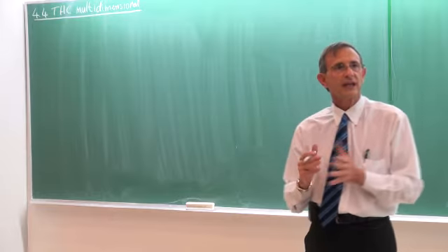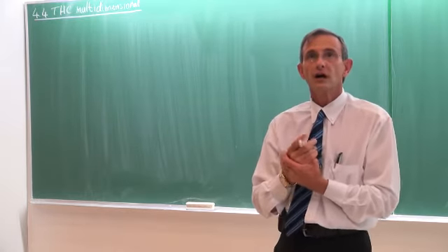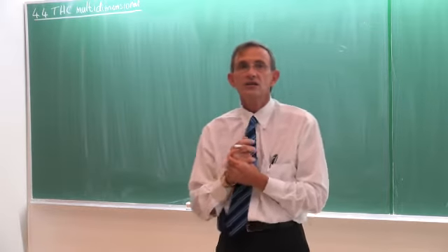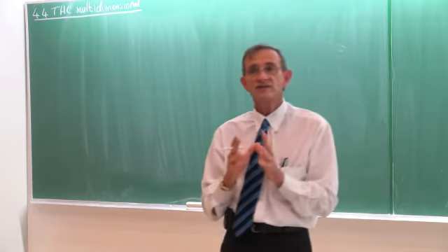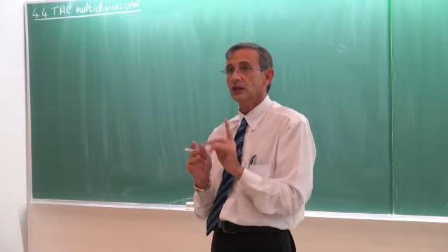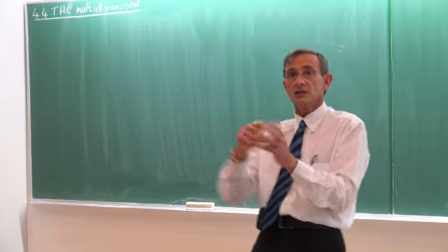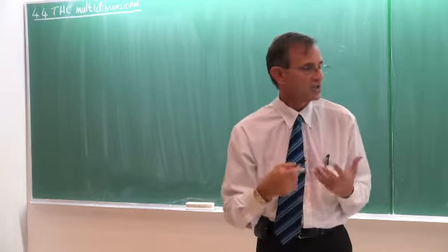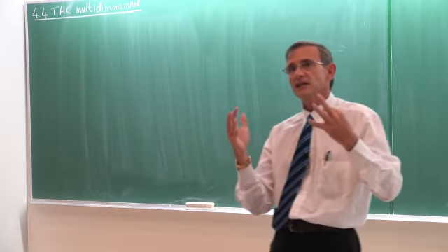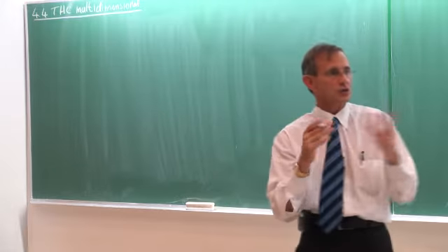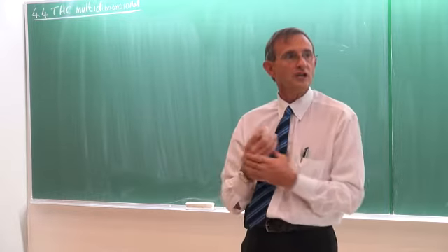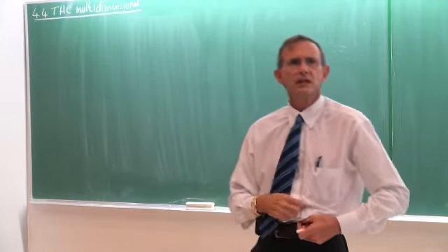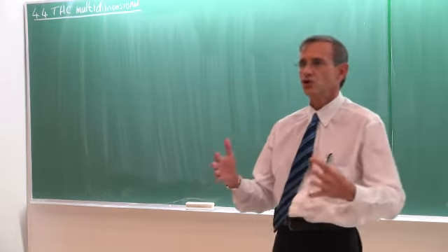The second approach that we can follow is to look at long plane walls, long cylinders and spheres, and the result of that is that the heat transfer can be in one direction only, not in two directions, and that is why everything should be so long. The result of that was a set of equations which ends up in a Fourier series that we need to solve. And if tau is larger than 0.2, then the error would be less than 2% if we only use n equal 1 as a solution.